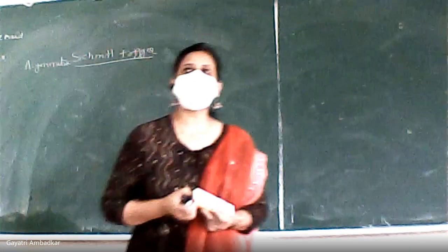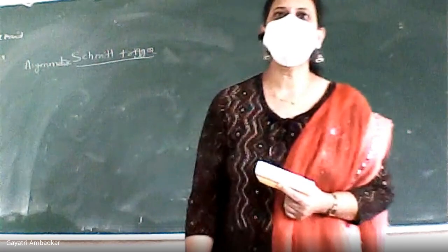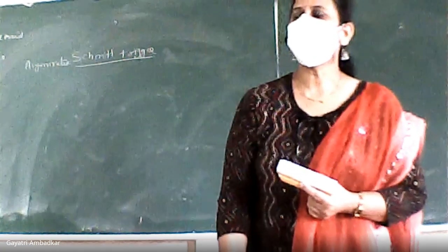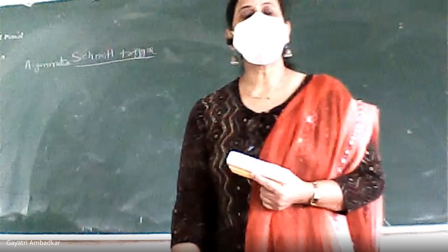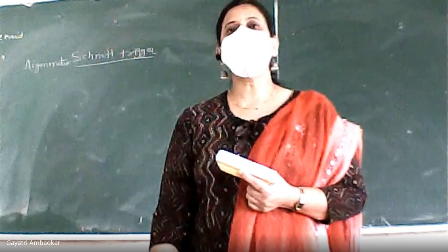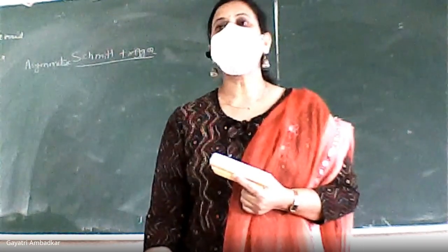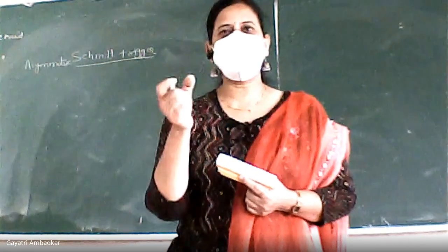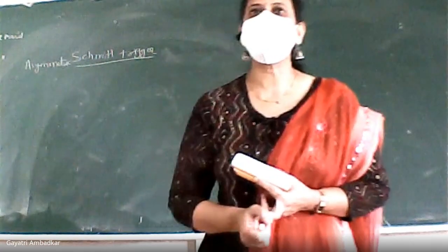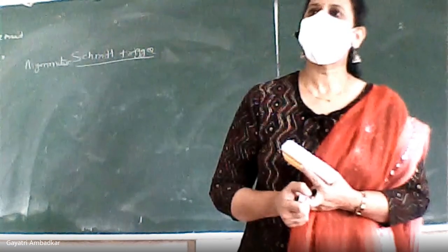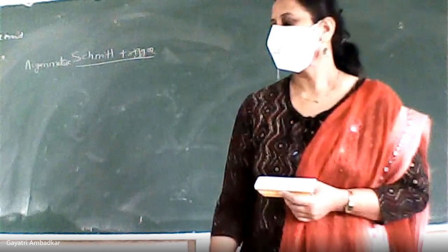The Schmitt trigger which we have seen before was a symmetric Schmitt trigger. Symmetric Schmitt trigger means the square wave you got as output, where the on time and off time of the waveform were the same. Okay, that means 50% duty cycle. What is the duty cycle?